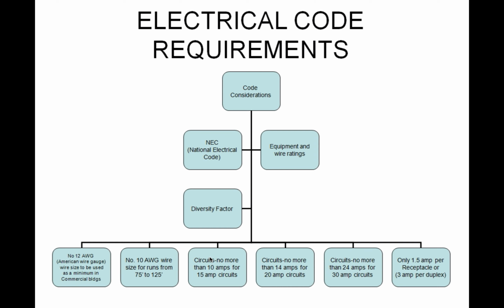Alright, so you would expect that most of the Con Ed cables that are around the city are these huge cables, whereas by the time you get to what's supplied into your wall socket, it's a very thin cable, and we'll go through some of the cable sizing. So typically a 12 gauge or number 12 AWG, American Wire Gauge, is the most typical size of wiring, not only in commercial applications but home building. Sometimes number 14 can be used, but typically it's number 12.